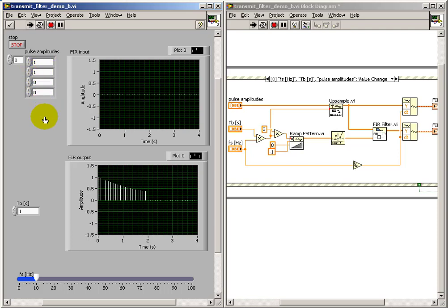So here's the beauty of using this FIR filter approach. What I'm doing now is hitting it with 2 distinct impulses. So we generate the beginning of our first pulse, and then we superimpose the pulse for the second bit interval, but we do that even while we're still working on the pulse from the previous interval. So the filter automatically handles that superposition that we need.